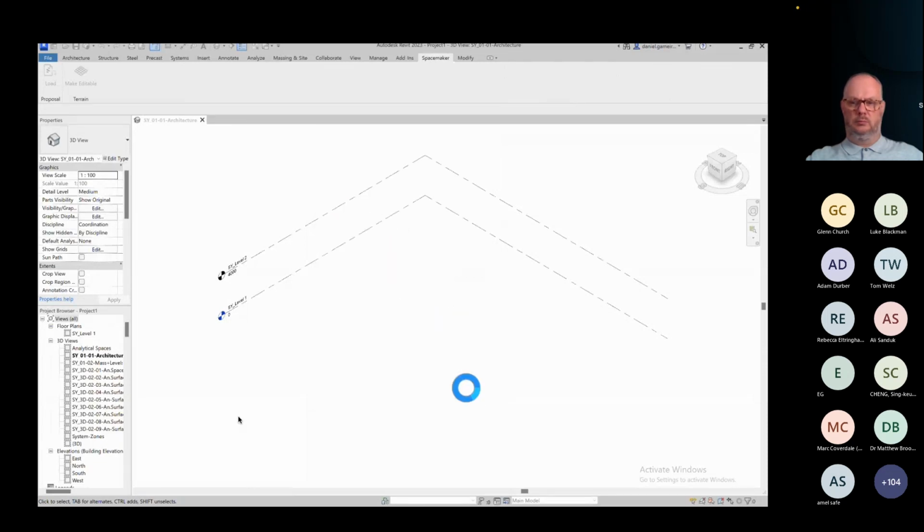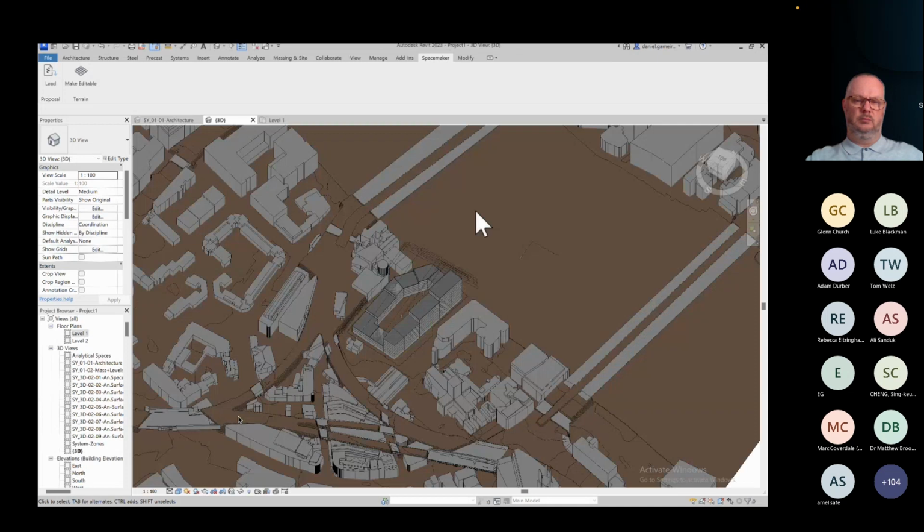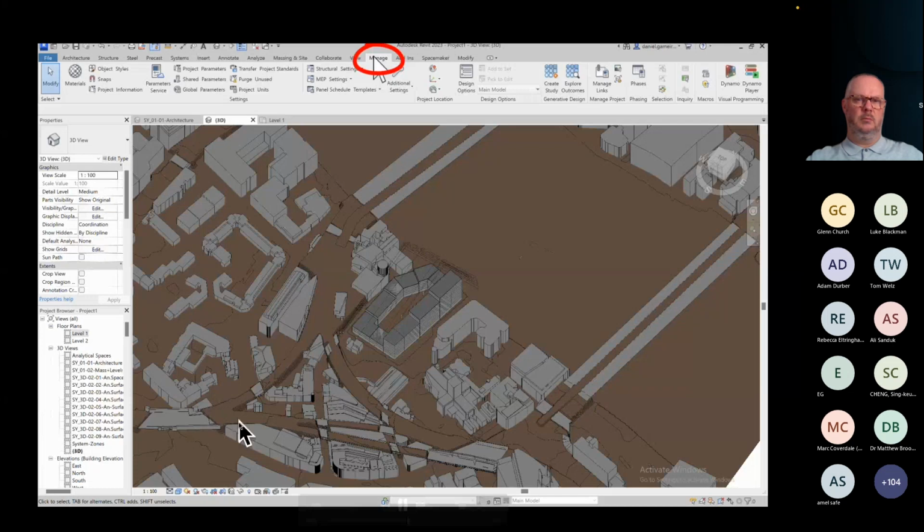And the coolest thing, in my opinion, is that it's not like you just get all the information, but this information you get is actually native to Revit, right? It's kind of insane. So all the walls, slabs you are seeing here are Revit families. What you could do? Well, you could just, for example, apply the build-ups that you have developed in-house, right? And you start immediately enriching this BIM model, and you get immediately automatically levels, grid systems, rooms, everything is actually created automatically. And of course, you can tweak exactly how you want to do these things.